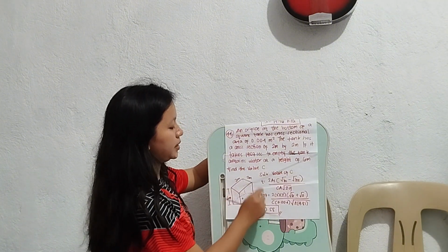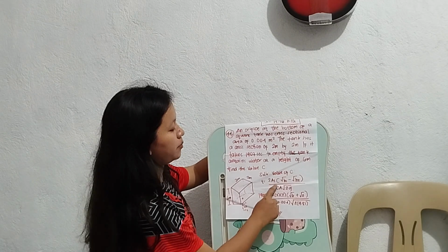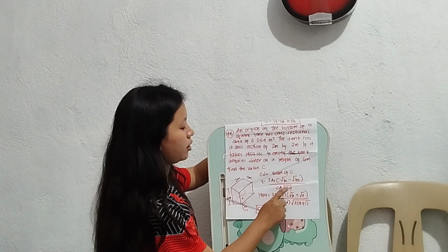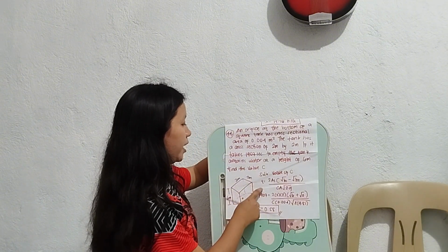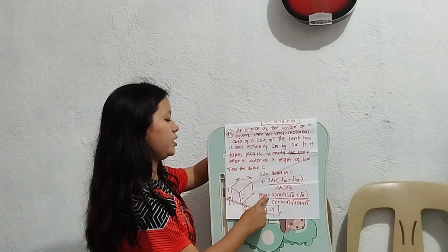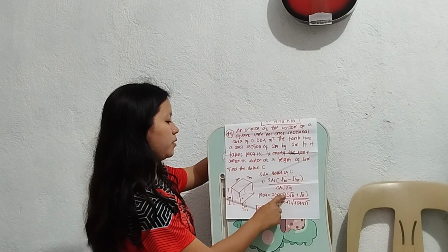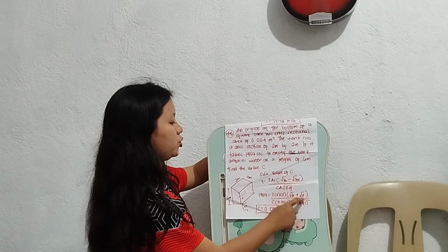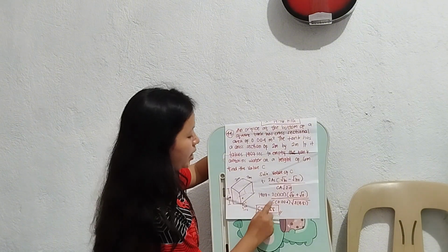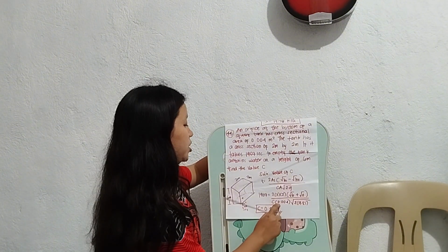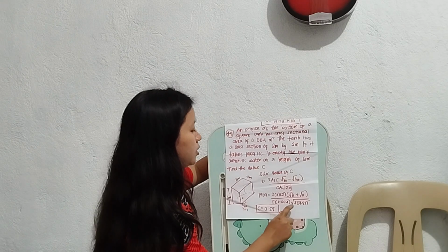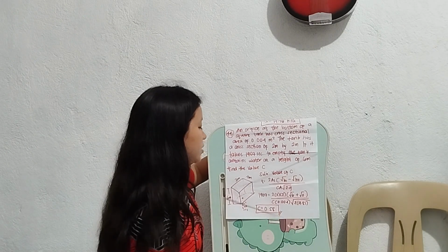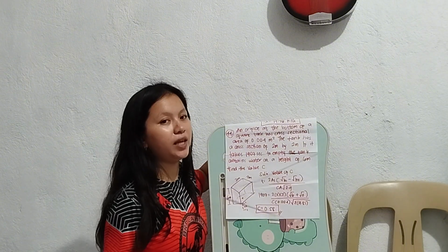So our formula is T equals 2AS times the square root of H1 minus the square root of H2 all over CA square root of 2G. So the time is 1,907 equals 2 times the area, 2 times 2, times the square root of H1, which is the 6, minus the square root of H2, which is 0, all over the C times A, which is 0.004, times the square root of 2 times 9.81. So the answer for the value of C is equal to 0.58.